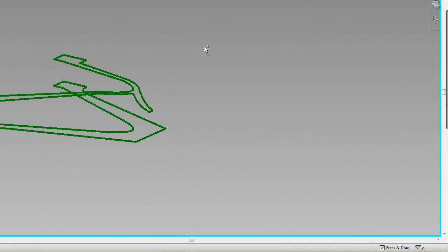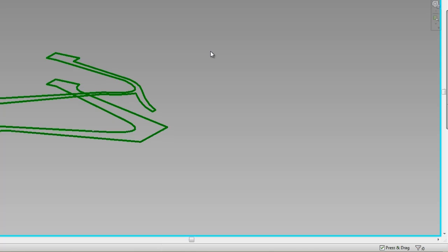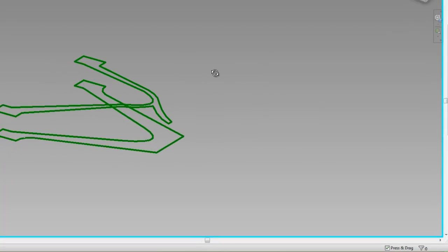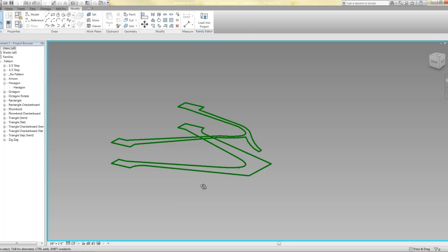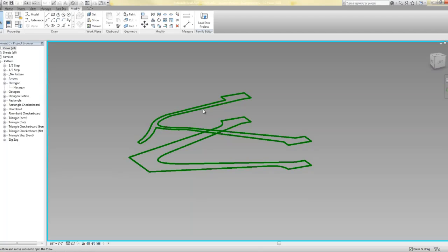So what we've done here is we're working in a curtain panel pattern-based family. And this family lets us use control points to instantiate a pattern we build in this environment onto a curtain panel system. To simplify this attempt compared to the last attempt, I focused on using two rail curves as the basis